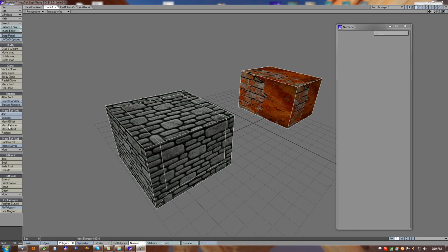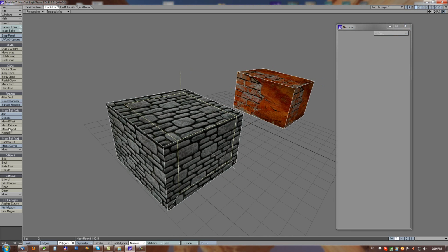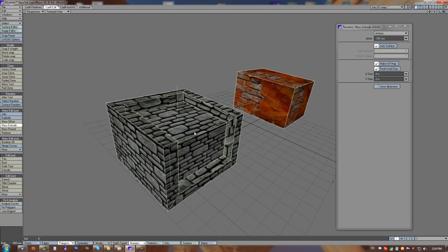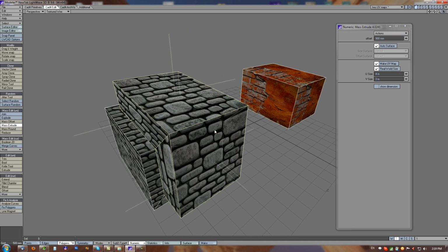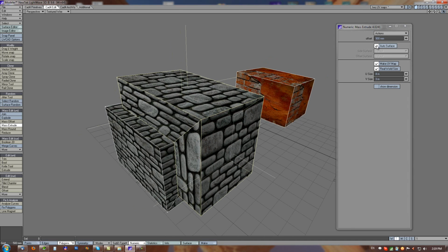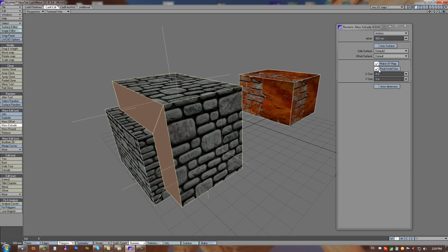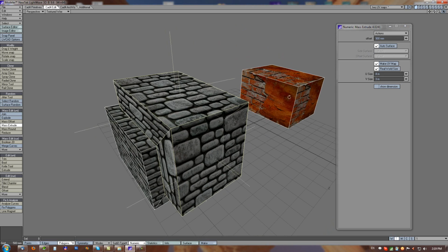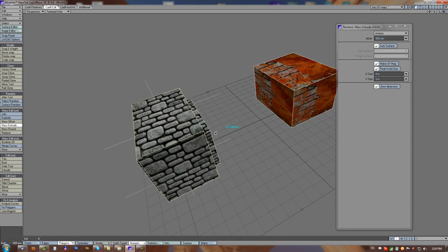Next is a mass extrude. So it works on selected polygons. When it is applied, it creates a nice extruded object on the selection, and it is also UV map compatible. So we can even set individually the side surface and offset surface, or keep it as automatic surface, and we can show the distance of extrusion in the numeric panel.